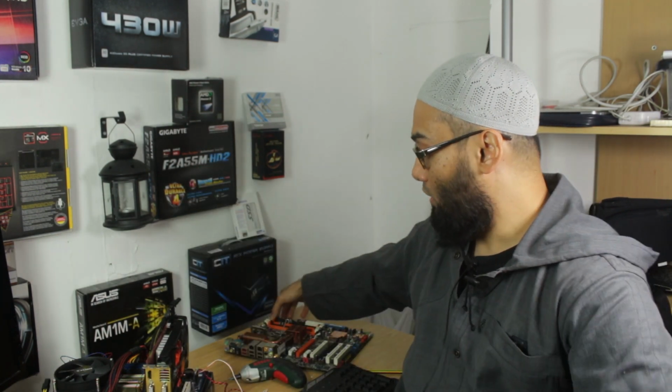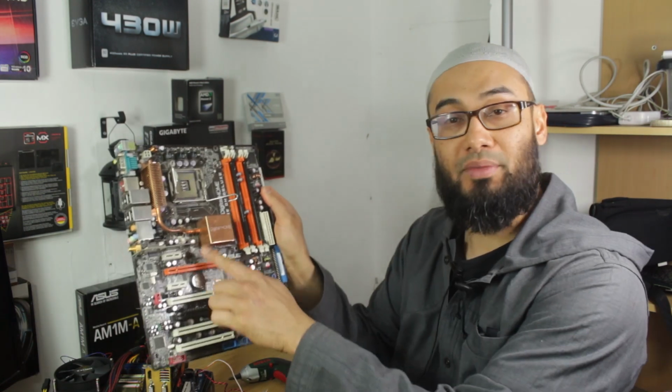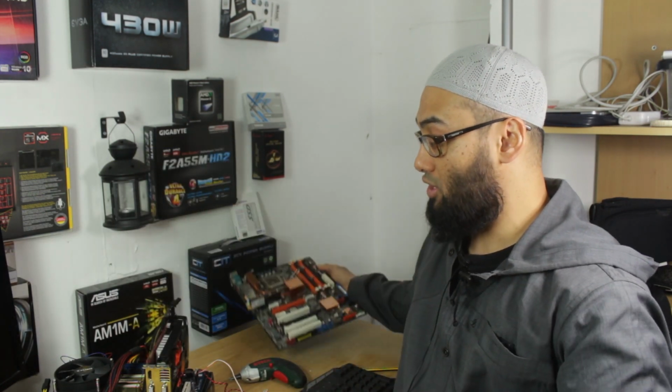Right, there is a type of supposed motherboard tester. I don't know the exact name of it, but they use ISA and PCI cards. So it's usually like a little card you insert into one of the PCI slots, right? And it's got 2 digits or 4 digits, and it's supposed to give you some codes, and you check against a manual, and then depending on the code, it will give you the exact problem on the motherboard.